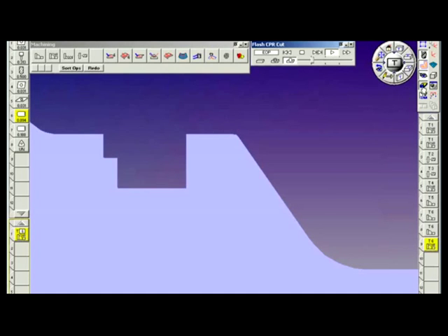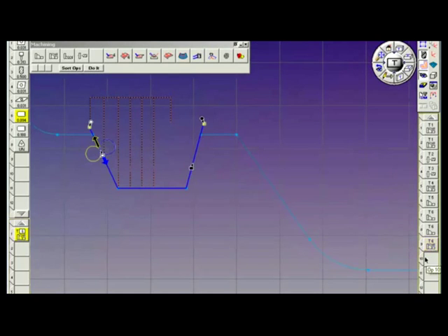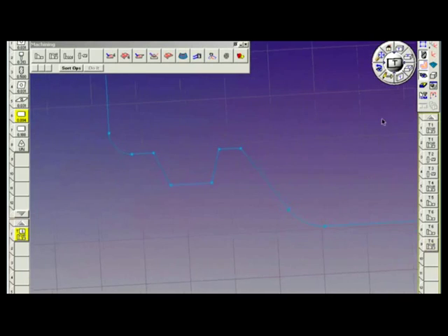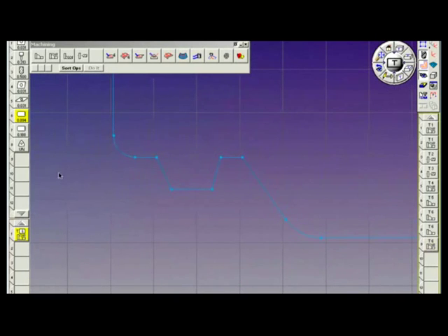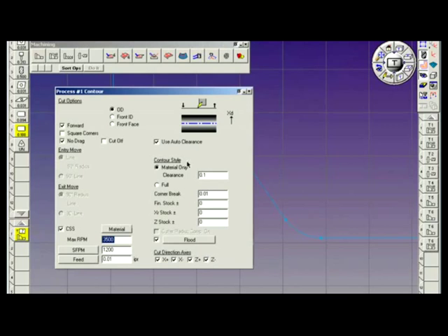All right, turn off rendering. We're satisfied with that result. We'll take and throw away the process, and we'll finish this groove with the larger insert as a contour cut. This cut will be a no drag, corner break of 10 thousandths.